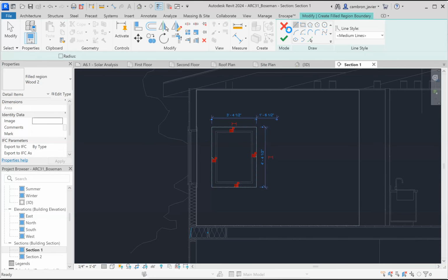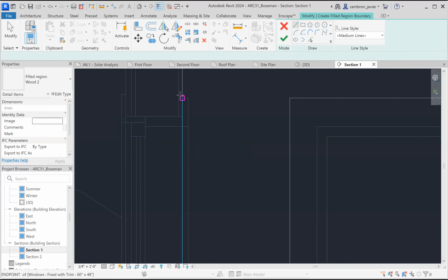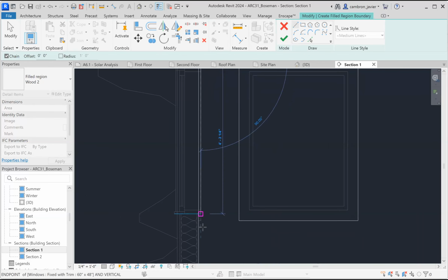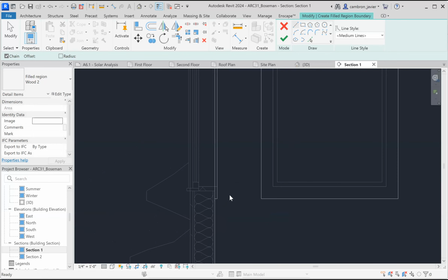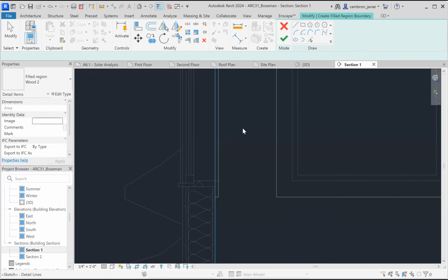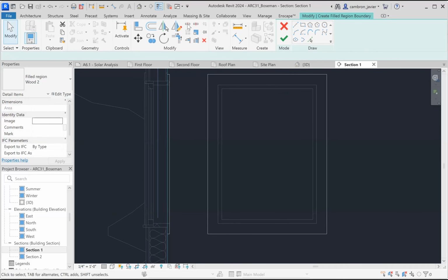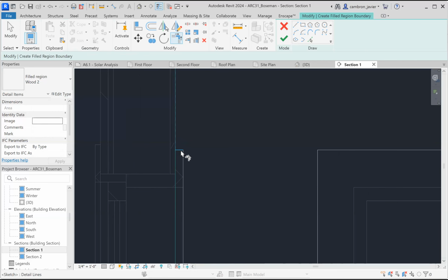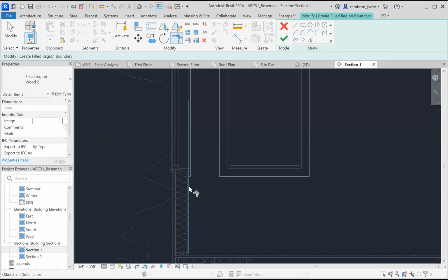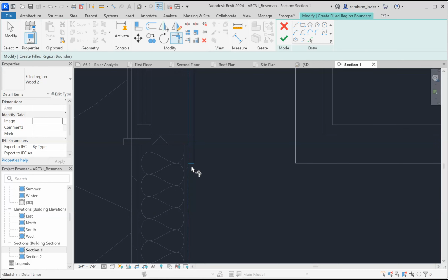And then I'm going to use my line tool to cut around the window frame. Okay, just like that. I'll take this line and split it. Oops, I clicked on the wrong one. That's the one I want. Okay, so now I'll hit trim extents, click there, click that line, click there, and click that line.